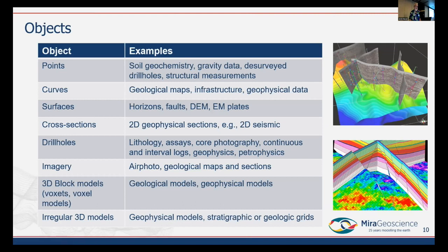And the top image there is just showing a 2D seismic section, which is not a straight line, it's a curved path, often shot along roads or something like that. And if you want to avoid introducing distortions into your data, you don't want to project that onto a flat plane. If you project the curved parts of that line onto a flat plane, you'll introduce distortions.